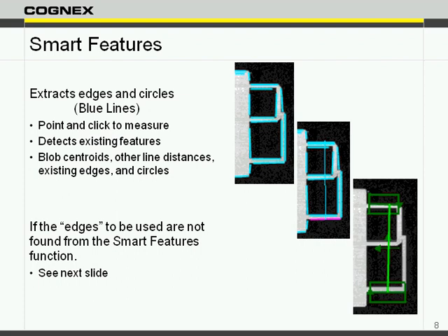Now with version 4.1 with EasyBuilder, right within EasyBuilder, it will show you all of the edges or all the features that it finds in blue, the top picture here. Then all you have to do is take your mouse and go in and tell it which two edges you want to measure between. And once you've done that, they turn green like the last picture. You can see the little crosshairs telling you that it is measuring between the two.